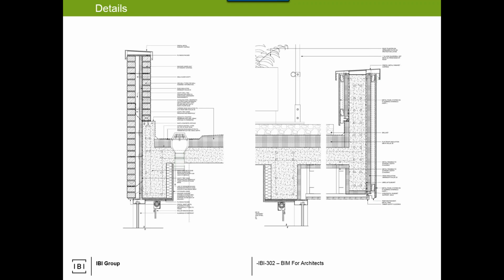So if you envision modeling is what you would get at 1 to 50, maybe 1 to 25, so that's quarter inch, or just a little greater in imperial. Then if you're getting to a 1 to 5 or a 1 to 10 detail, so a half inch or greater detail, you have to add the detail overlay. So you add more information so that it conveys it.